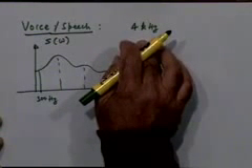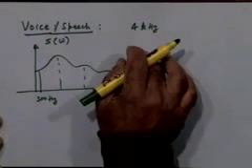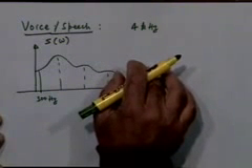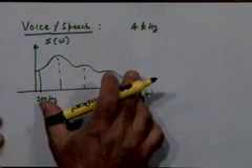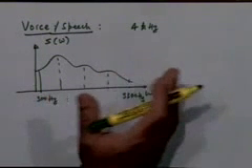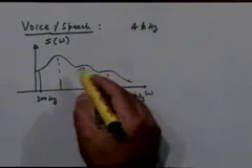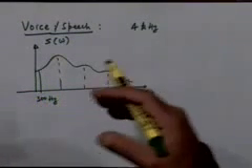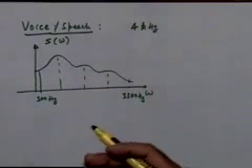Right. So the original point that I was making, from which we digressed, was that bandwidth is an important resource. The voice signal has a bandwidth of about 4 kilohertz, but it does not necessarily mean that the information conveyed by a voice signal when I am talking to you is proportional to 4 kilohertz, because this bandwidth is a property of the speech waveform that is coming out when I am speaking, right?